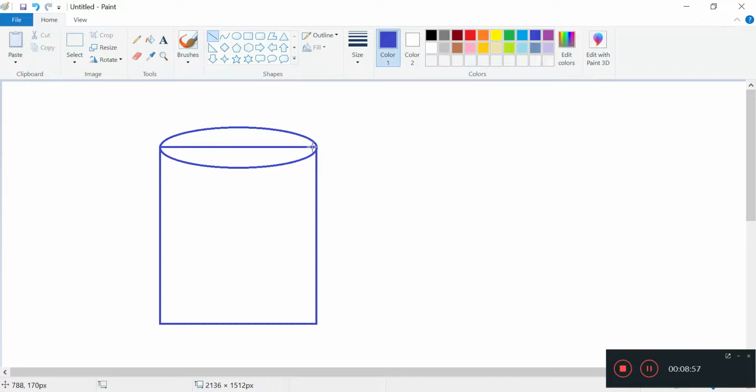Let me erase this away. Some form of cylinder here, and what we notice, if you have watched the snappyHexMesh videos, is that usually around the edges is where all the meshing problems start to occur. So the way to circumvent this is to do something called surfaceFeatureExtract, so that you can take care of these edges which are so nasty to mesh.